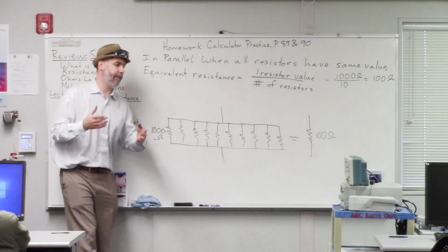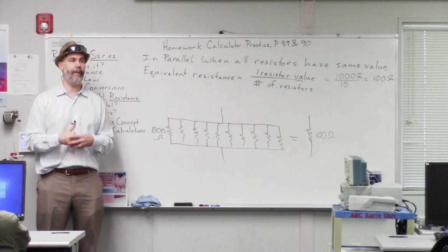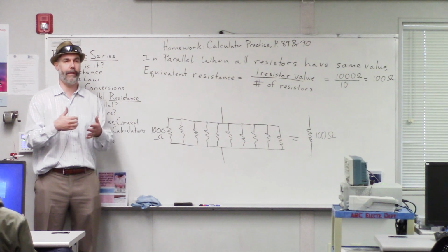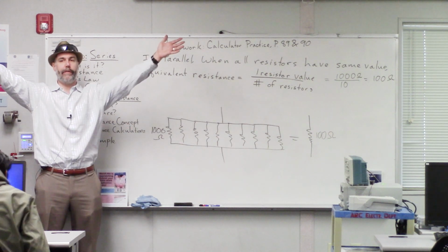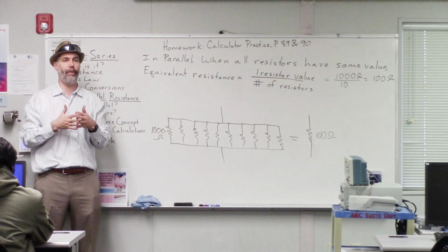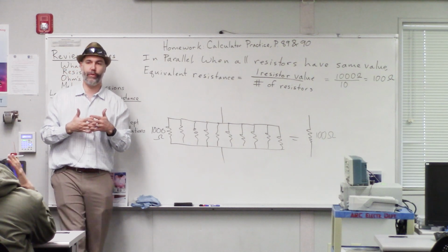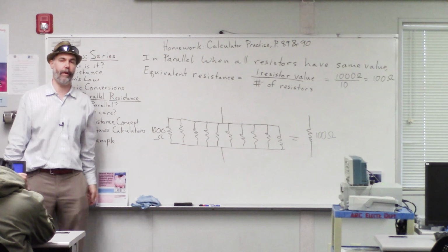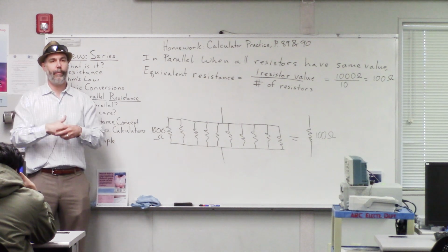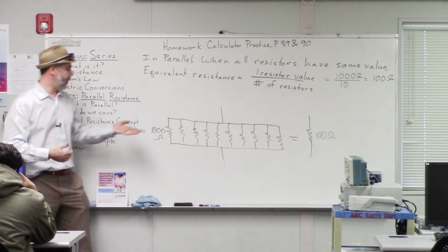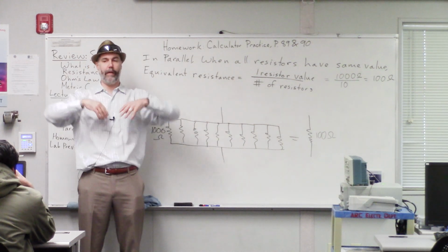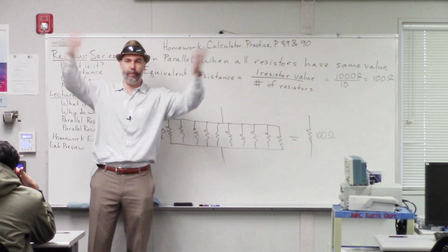So you might think, well, just disconnect the antenna. But it turns out that radios don't work well if their antenna is disconnected. The signal that was supposed to go out into that antenna actually bounces back and goes back into the radio itself and can overheat components inside that radio and damage or destroy your really nice, expensive radio. So you need to have something hooked up so the signals have somewhere to go, but you don't want to broadcast them out. So what people do is they use something called a dummy load, which is basically just a big resistor that's not an antenna. So it absorbs the signal without broadcasting it out.